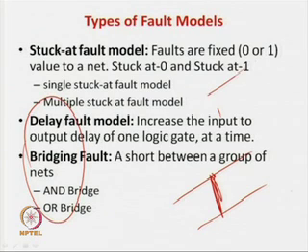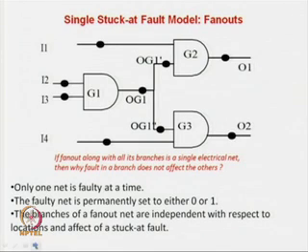Mainly we will see the stuck at fault, which is the most widely accepted fault model, because it has been seen that if you adhere to this fault model, a large number of faults of this nature and of a more advanced nature get captured. So, we will see this fault model. Let us see what a circuit with a fault model will look like.